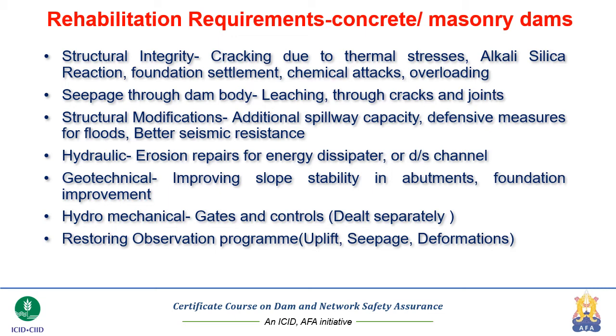As we have discussed earlier, cracking occurs due to thermal stresses, alkali-silica reaction, foundation settlement, chemical attacks, overloading, and some other aspects as well. This cracking has to be repaired, and for that specialized materials and techniques have to be used. Very large cracks, which are structural cracks and endangering the overturning stability of the dam, may have to be stitched with the help of pre-stressing mechanisms and then grouted. Some of the other cracks, like those generated out of thermal stresses or alkali silica reaction, etc., we may have to grout with specialized materials.